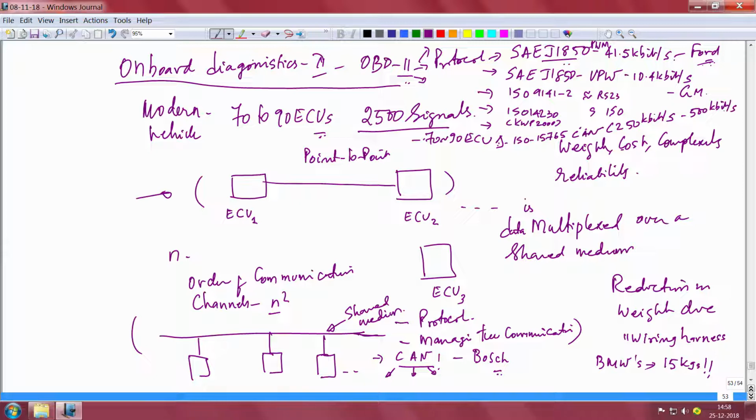And this is most popular. So, there are some voltage levels that the CAN specifies, what should pin 6 be, what is pin 14, and what is CAN H signal, what is its voltage level, what is the minimum and the maximum, all that is specified as part of the ISO 15765. Therefore, it is important to know this, and this, as I mentioned to you, was standardized. The CAN protocol itself was designed by Bosch.